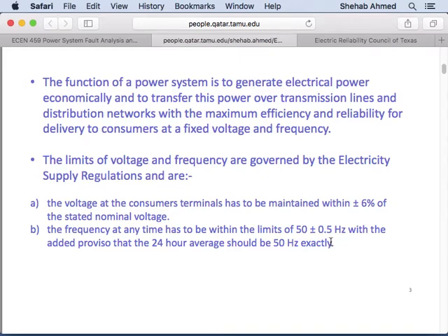At the end of the day, the speed that they're moving at should be an average of 50 hertz, right? So if he gets tired, the other guys pick up the slack, and they keep going forward. And they keep doing this all the time, right? You can never be all the same. All the generators in the power system are never going to be operating at exactly the same frequency, right? So they're always doing this. There's always a deviation in power angle, is what we call it. So it's always an average of 50 hertz, assuming that they don't fall out of synchronism, right?